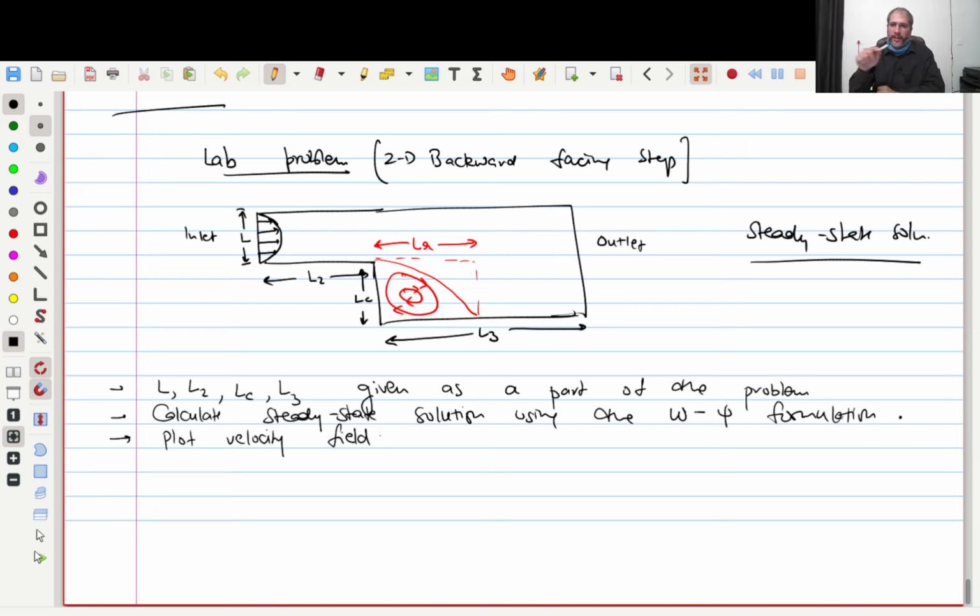But streamlines will not give the direction of velocity, they just give the lines, although we know the direction intuitively. There's another thing called the velocity field, which in plotting is called a quiver plot. It's basically a vector plot of the velocity field. So plot the velocity field, then streamlines. These will help us visualize the flow field. These are local variables because they are plotted at every point.